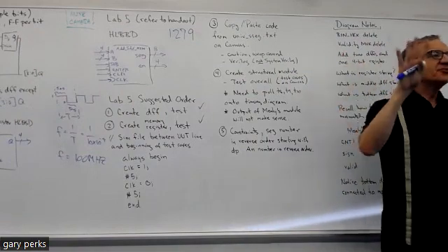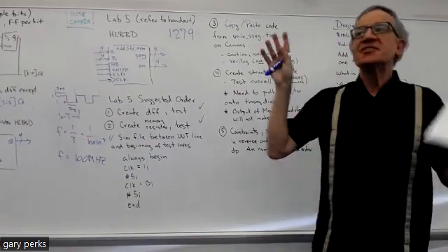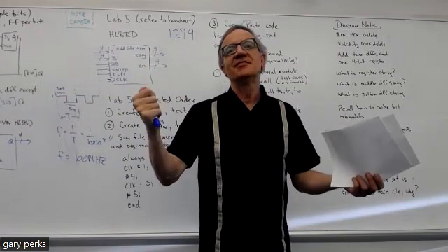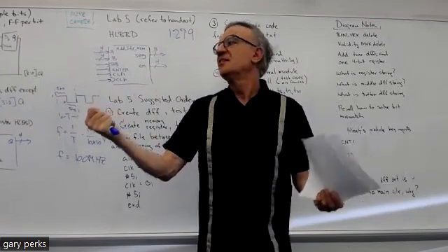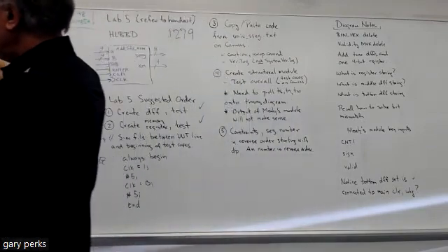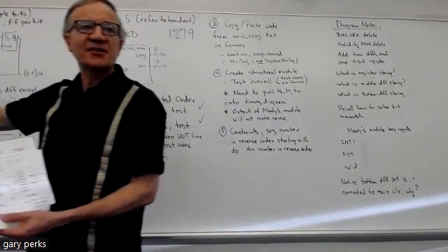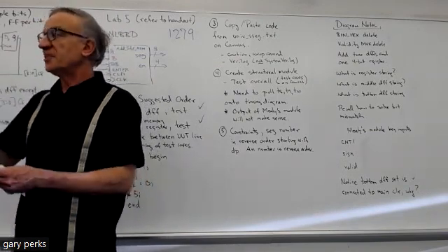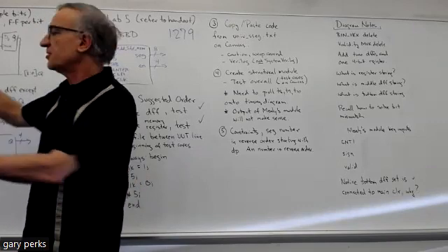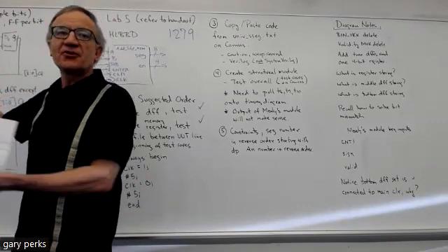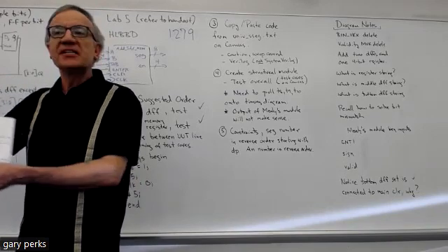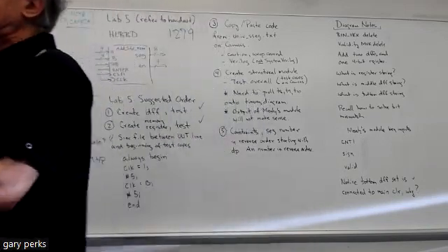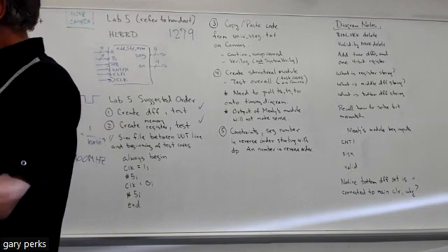Remember Dr. Benson's troubleshooting video. What was the big technique, the big thing you learned from that video and demoed to me? Drag and drop. You can take any intermediate signal and drag it onto the timing diagram. That's why Dr. Benson titled it the troubleshooting video: it's a very useful technique because you can trace the signal through your circuit, see where it first goes awry, and zero in on where the problem is.